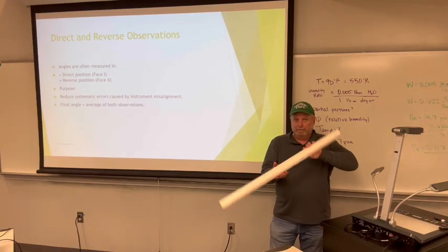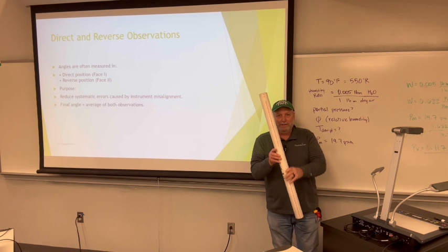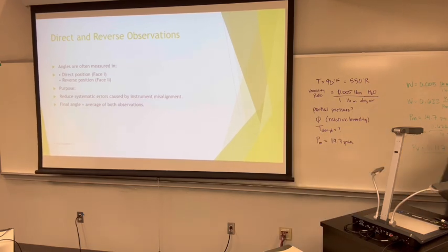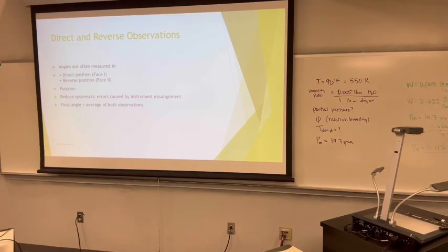Flop your scope. Don't look at yourself in a mirrored position here. That messed me up. You measure your angle over here. You flop your scope. You measure your angle over here. You're going to be the same distance off. So you're looking at two different angles. When you take the average, it's going to put it right in the middle. It works. Trust me, it works.